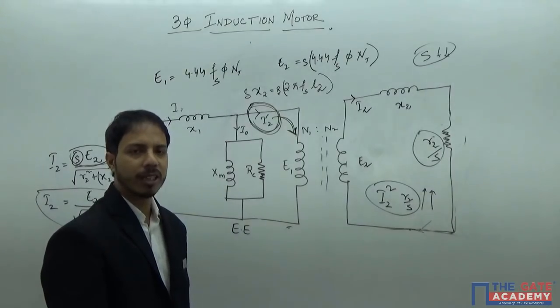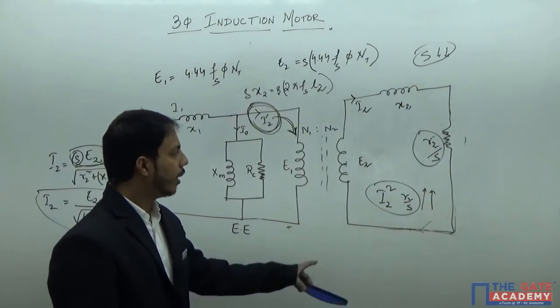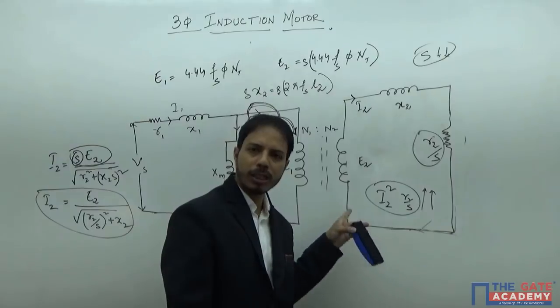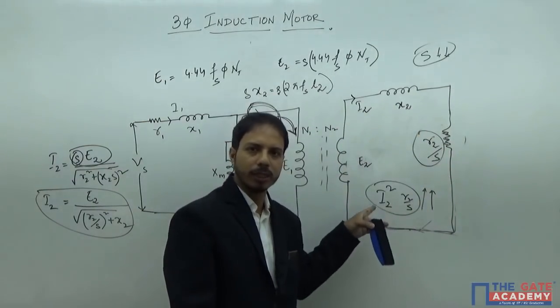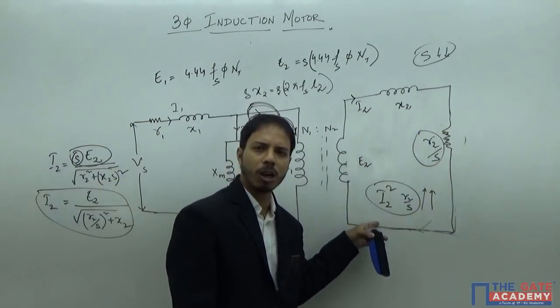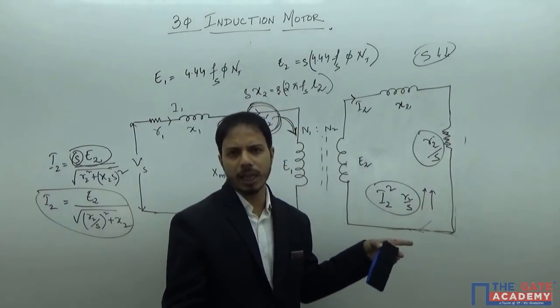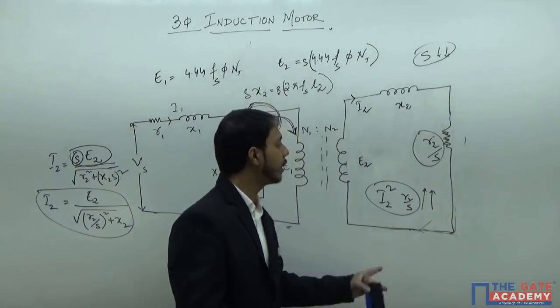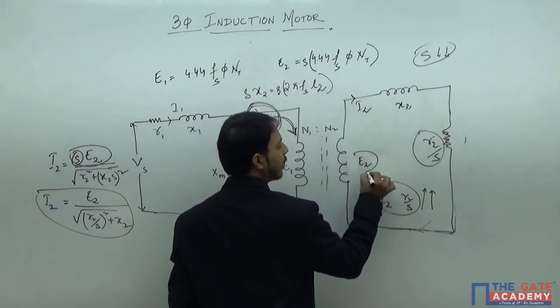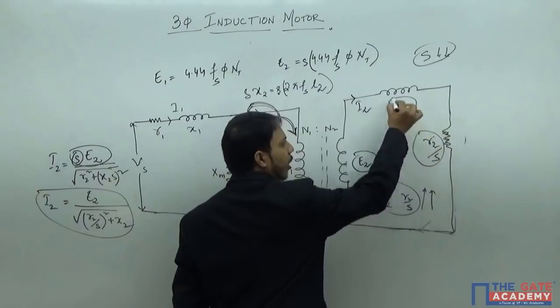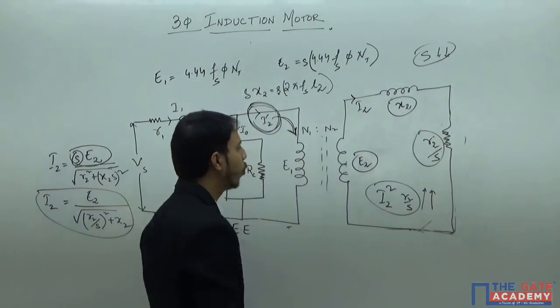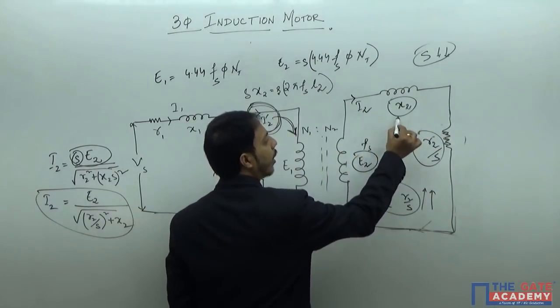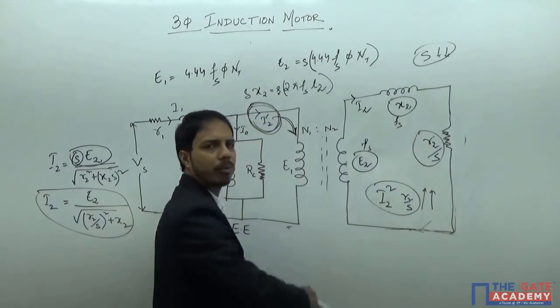So now what I have done here is, this circuit is not only the electrical circuit of the rotor. This is the representation of the electrical as well as the mechanical circuit of the rotor. And since you see now the frequency, this is a term which is dependent on frequency, and both of them are f of s. And this is an independent term of frequency.